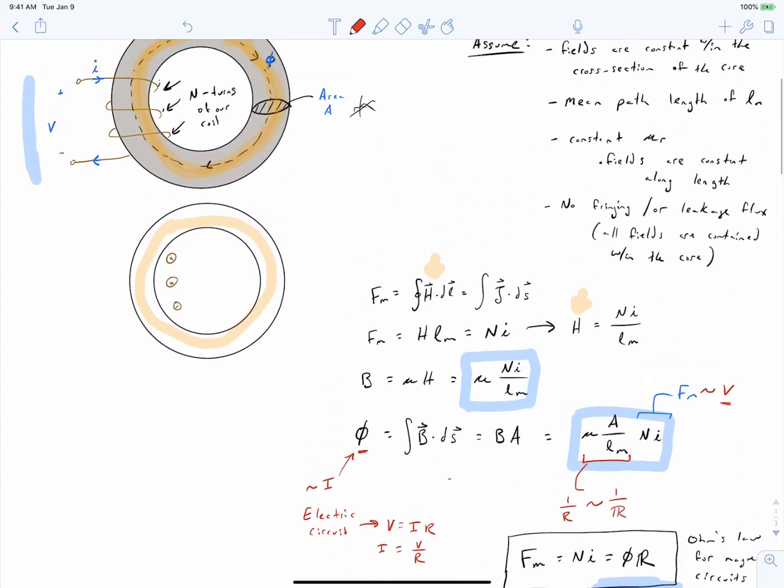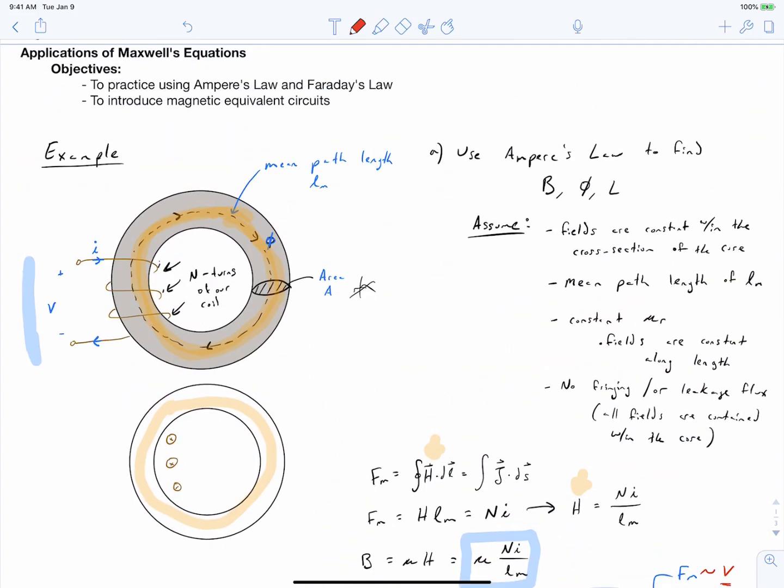Alright, let's refer back up to this diagram. We had previously remarked that the polarity of EMF is defined so as to produce a current in a direction to oppose a change of field. So if we assume that we have some kind of passive resistor connector here, or it could be a short circuit, what polarity would your EMF have to have in order to drive the current I? In order to complete this path, we would need a current going across our resistor like this. So our EMF would look like this. We'd have an EMF source that's pushing current through the resistor upwards and into the terminal to make the blue current path flow as indicated.